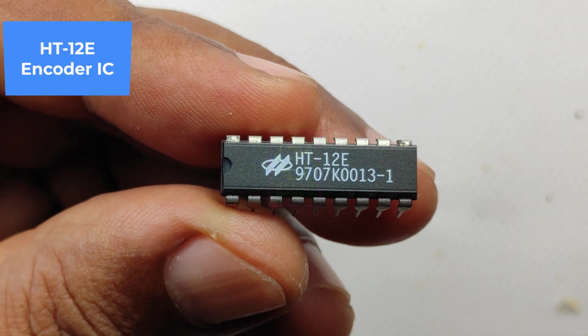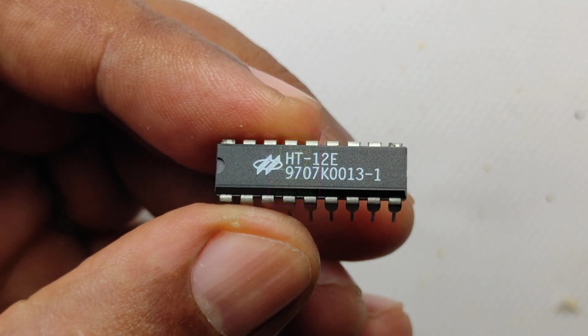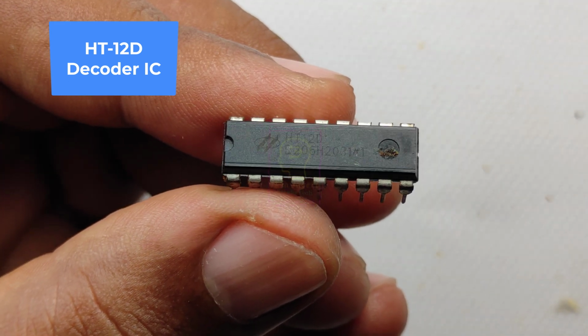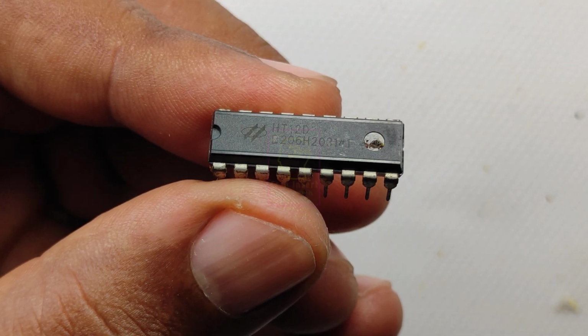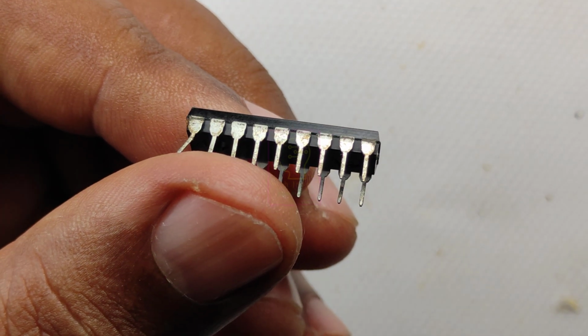This is encoder IC HT12E. This is an 18-pin IC and this is its counterpart IC, that is decoder IC HT12D. This is also an 18-pin IC. Both are 4-bit data IC and also 8-bit address bits are available. We are using encoder IC in transmitter part and decoder IC in receiver part.